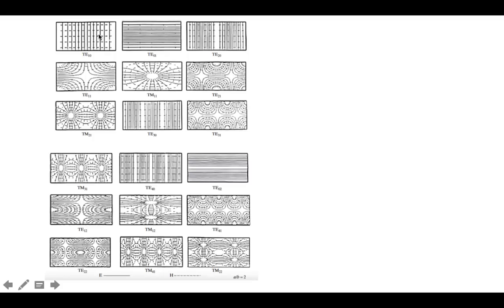When we're looking at a slide here in a bit, I just wanted to point out that in this particular example, this is a cross-section of the waveguide. So basically the wave will peak in the middle and go to zero at the walls as far as the intensity if we look in the horizontal direction. Here, notice in the TE20 mode, we have two peaks, one here and one here. If we're looking at the magnitude, then we would come up and come down, but basically looking at the field intensity, we have peak and peak.